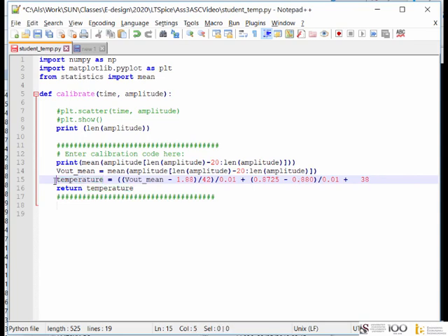And then you need to figure out what the calibration constant is. So first you do it analytically, and then you can go and twiddle with it or do it empirically. Analytically means you do the calculations. The one that I'm showing you on the screen now is the calculation, but you can also then do what we call calibrate, where you do a few samples, you measure them, and calculate a transfer function between the input of the sensor and the output of this transducer of yours, or this sensing system of yours.